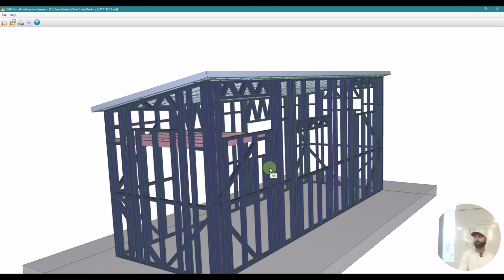We've done enough projects now where we have a pretty big catalog of structural connection details that we're just recycling at this point. We've got floor joist tables, roof joist tables. We've got span tables for our 2x4 at 24-inch centers, 16-inch centers, 12-inch centers. So our drafting team has all of the tools that they need to know when we have to up the gauge, up the steel profile. We already kind of know what depth of trusses are required at various spans. So by the time we're getting it to our engineer, it's just a stamp. Yeah, we're almost never changing the frame design at this point.